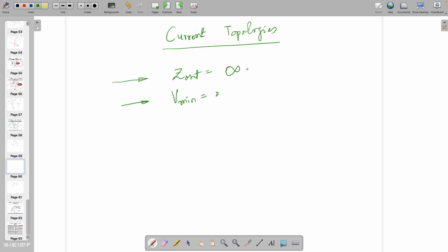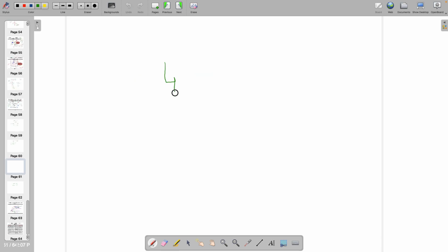However, it's very difficult to achieve infinity. You know that various topologies are available. One of the simplest topologies is this one. This looks very simple. However, when you are designing, it is important that you use a multiplier. If there is some W by L with multiplier 1, then with some value of multiplier, let's say n times IREF, you can have it over here.